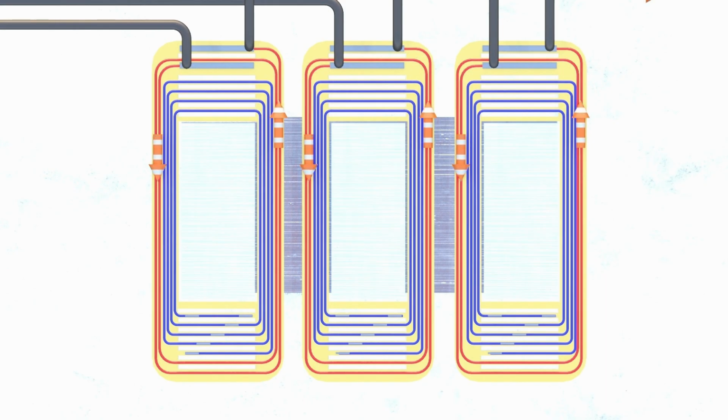The combination of primary and secondary windings, as well as the additional air gap with its spacer plates, which are guided by a common 3-legged iron core, form a combination of a series choke and a stray field transformer, technologies that initially don't differ from the already long-established designs. And in terms of functionality, there are initially no significant differences compared to proven technologies.